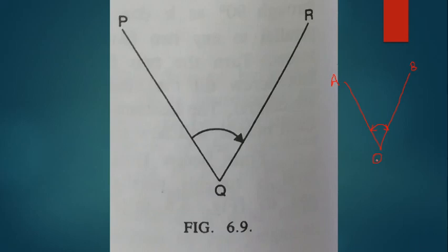For this I can release the lower clamp. Why lower clamp? When you release the lower clamp and tighten the upper clamp, both plates move together and therefore there will not be a relative change. That means the reading will not change.